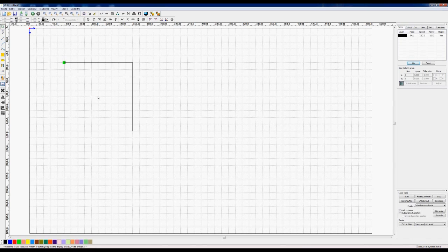Now, for the purpose of this exercise and making it so much clearer, what I'm going to do is double click on this little object, and we're going to put our handle, instead of in the middle where it is at the moment, we're going to move it to the top left. So now we've actually got a positional handle for this object at the same place as the program writing handle. The program writing 0, should I say, because it isn't really a handle, it's just a datum point. I just want you to remember, look, we set this position of this center handle up at 100. When I look at it again, this object, you watch what happens to X and Y. They're 50-50.